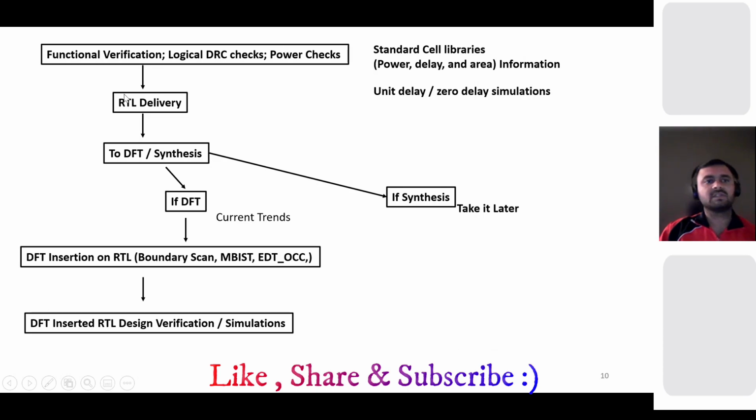Okay, so once the functional verification and logical DRC checks are done here, you use the standard cell libraries, because you have only a behavioral model as of now. You don't have any flops or gates model. So here basically TSMC or the foundry provides you the cell libraries which have the power, delay and area information in them. And then you use it to verify your logic. And then you do the RTL delivery. So whatever you have designed, you deliver it to the DFT or synthesis team or to the physical design team.